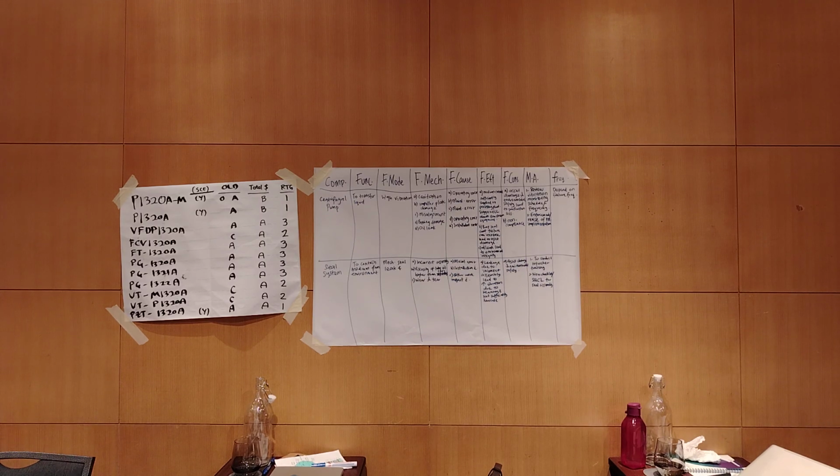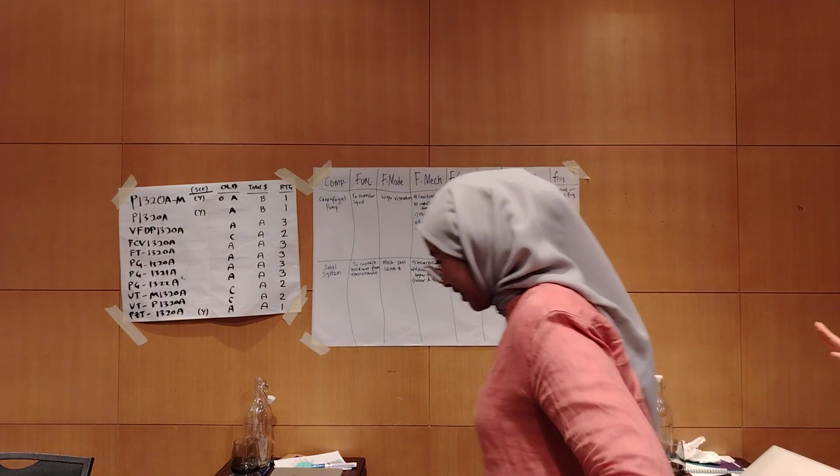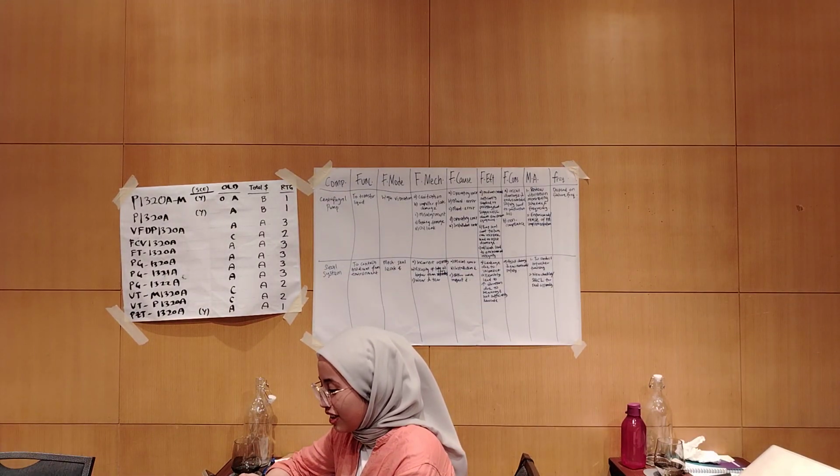If you want to do it in detail, please do like this. But usually people just put pump trip, because it's immediate. If it's detailed, then I'll have tons of components. This is only two conditions, that's why they can do it like this. When they have a lot, they tend to use keywords.